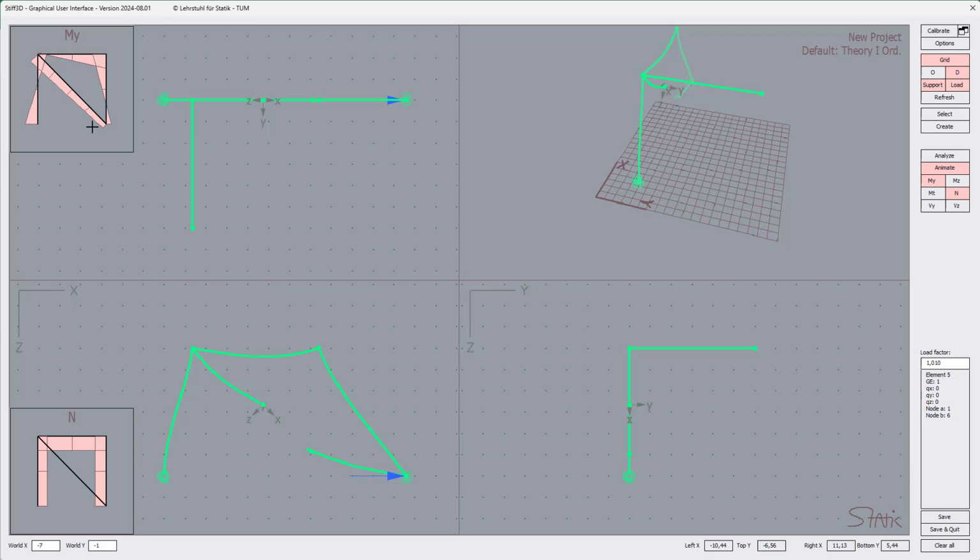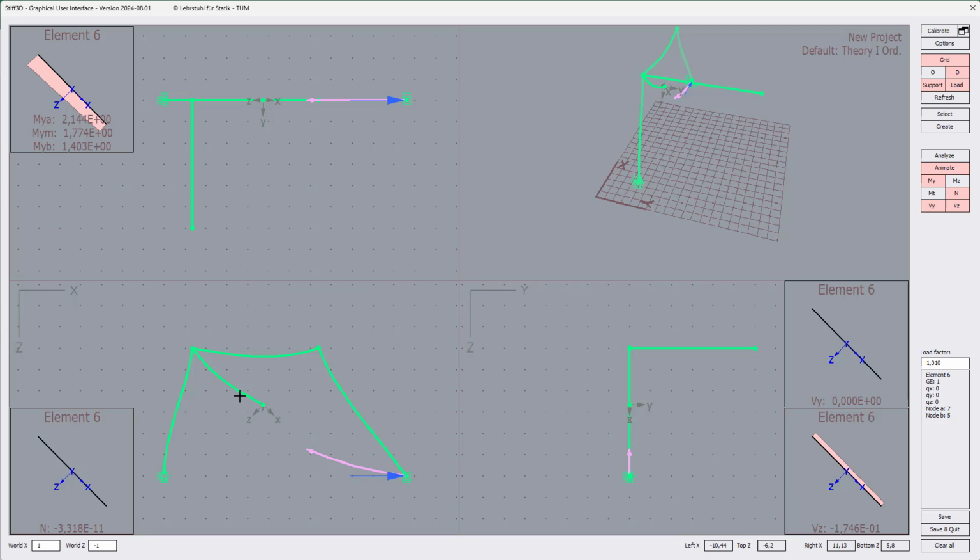It's coupled, everything is being transferred, and that's exactly what we expect of a hinge only working for the longitudinal deflections. We could also control the shear forces. The shear force for this element, you also see, is nicely coupled. The shear force is the same constant value along the complete diagonal.